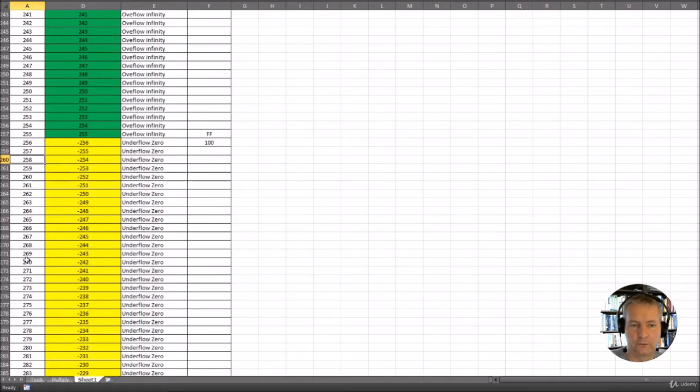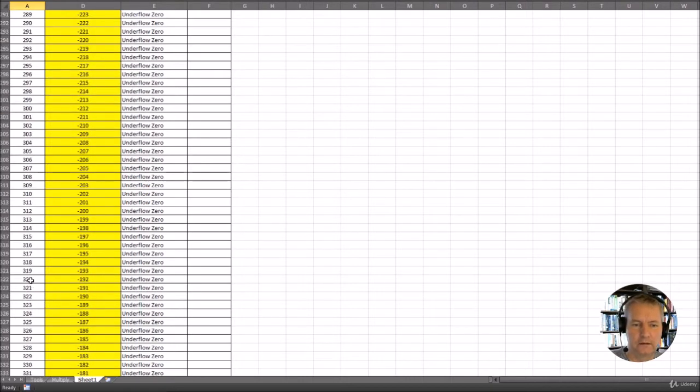For example, 300 plus 300 is going to give us 600, but 600 is outside the maximum value you can get in the adder. The adder will only go up to 511 because it's a 9-bit adder. So in effect we would get a carry bit, and it would be a flag saying, look, we've carried a value out, and then we've got this other value here, which is the output.